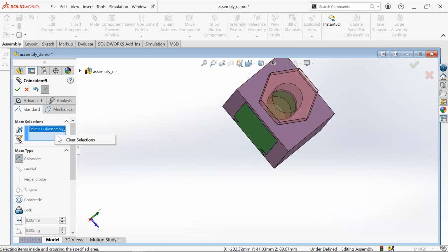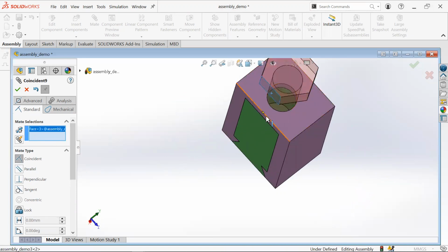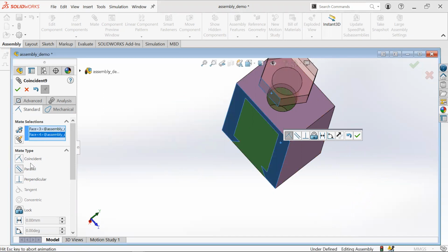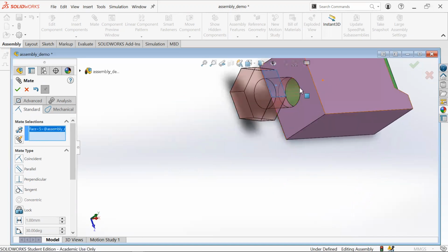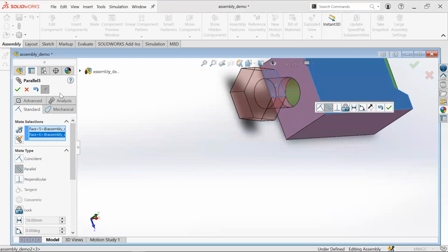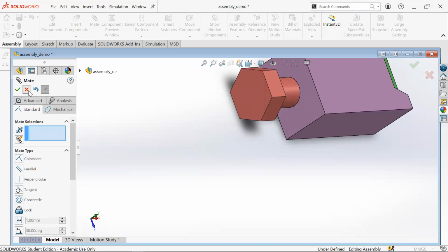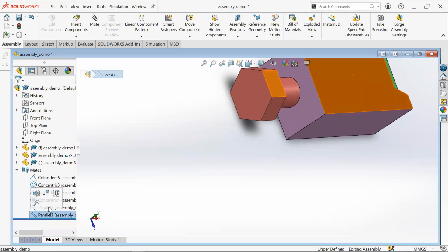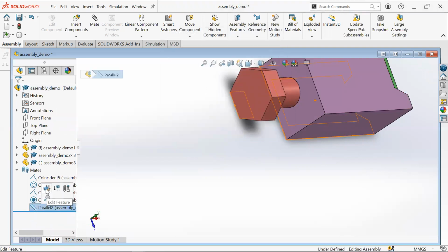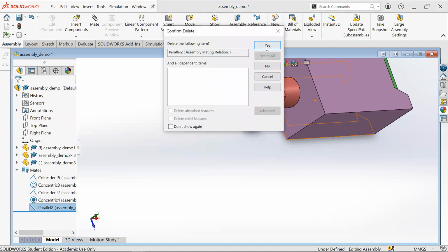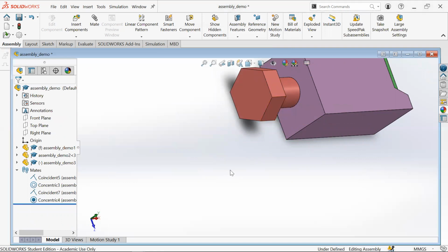And similarly to sketches, I'm pretty sure you can also, here, let me just try this just to be safe. Hit this, hit the surface, hit parallel. Okay, I'm not sure if you can over define this. Let me try this one more time. Let's say I want to do this and this surface here, parallel, check. Okay, so it doesn't seem like you can over define, at least to my knowledge. Well, it's not easy to over define in the assembly environment, but it will make things more annoying for you as you may want to free up certain degrees of freedom in the future.